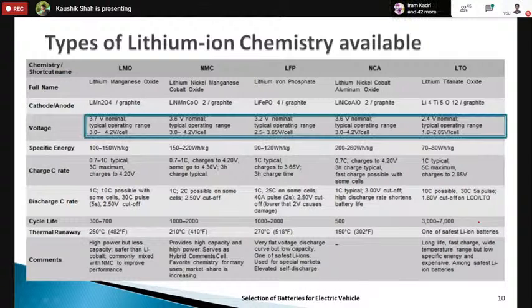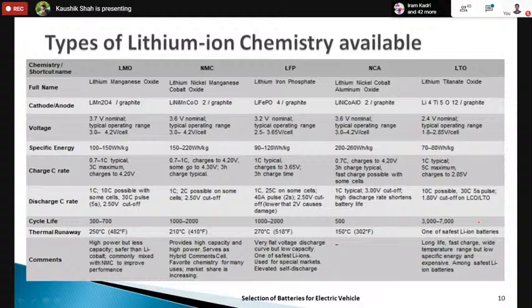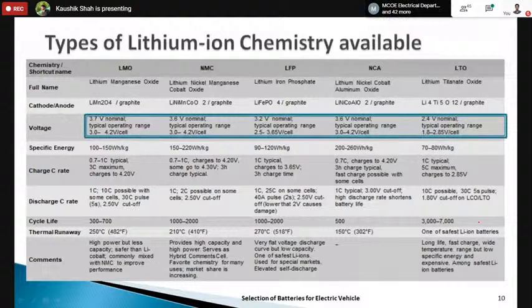So look at this LMO. I think it is mentioned in the earlier session also, that this is lithium manganese oxide. I was hearing some questions maybe 5 minutes ago, so I can grab it. I don't want to repeat again. But the important thing to look at is the voltage. Now, when you look at the specification which I mentioned earlier, one cell is 3.7 volt if it is LMO, whereas if you go to the LTO, it is 2.4 volt.